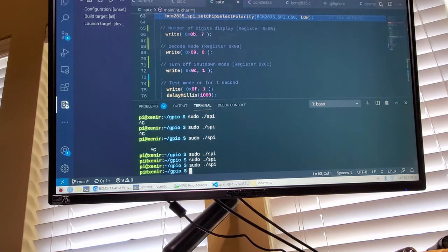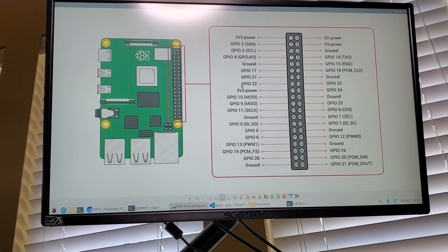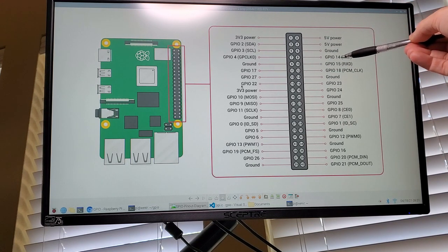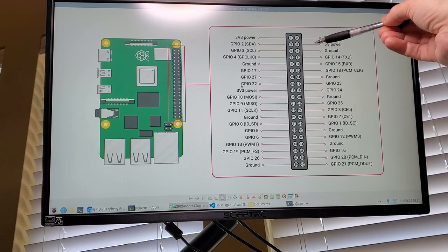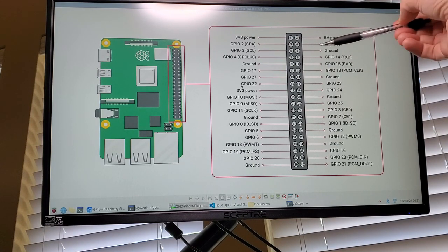The Ubuntu is pretty straightforward on the setup. There are some things you have to do on Pi to set this up, so I'll go through that quickly, and then we'll do the GPS demo. Okay, so moving on to Serial, which is probably one of the most straightforward examples here. You can see the mini UART is exposed on GPIO pins 14 and 15. TX is from the Pi to the serial device. RX is from the serial device to the Pi.